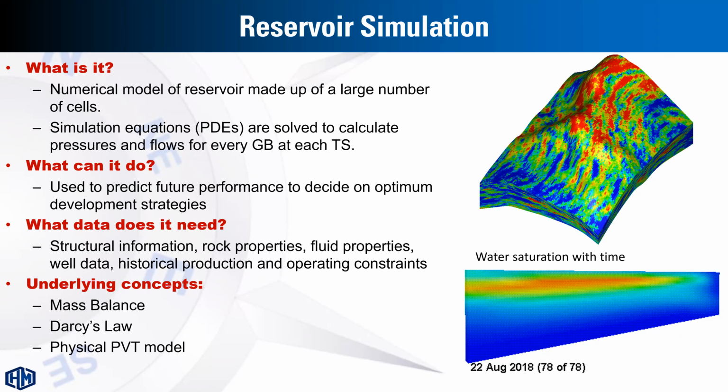A PVT model is also required to characterize the fluid properties like the oil density, oil viscosity, and so on, versus pressure, because with time we have a reduction or depletion of the average reservoir pressure, and also a reduction of pressure from the average reservoir pressure to the bottom hole pressure and to the wellhead pressure and so on.